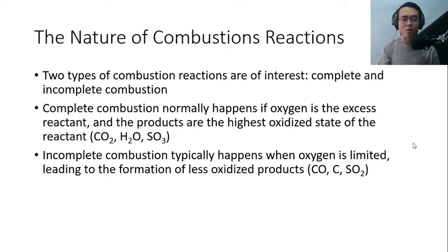But for combustion reactions, we have specialized terms wherein when we are referring to complete combustion, we are referring to the products being the most oxidized form of the fuel. So if you have the basic carbon hydrogen fuel, the most oxidized form of carbon is carbon dioxide. The most oxidized form of hydrogen is water. And if you have some sulfur in your fuel, its most oxidized form is SO3. So if those are the substances that you see in the product, that means that you have a complete reaction.